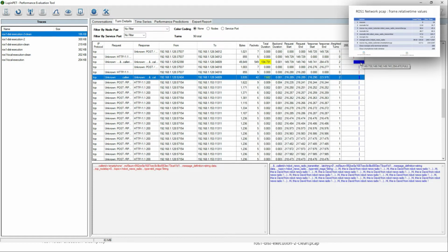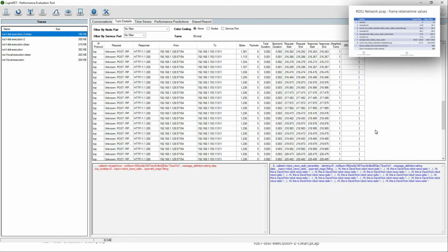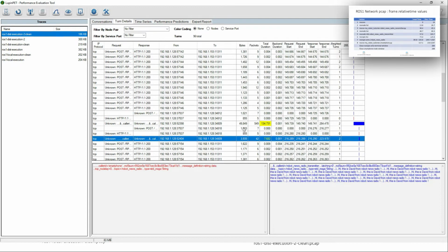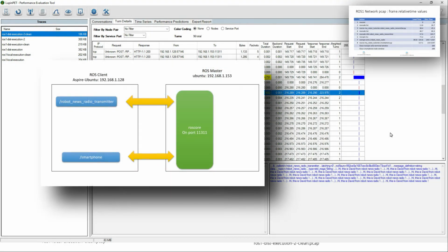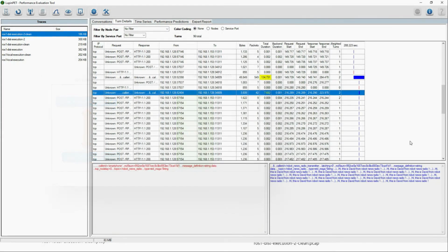So it worked differently from this one up here. So again, the ROS topic echo seems to not stop the subscription the way the proper subscribers do. So maybe a bug in there, but the rest of it worked the way I expected. The remote client will talk to the ROS master while it's setting up connections. Once publishers and subscribers are registered with the ROS master, then communication between the two goes directly on the same machine.